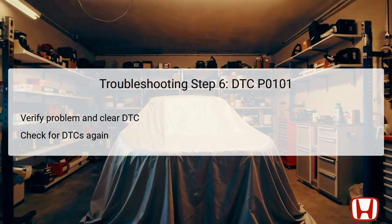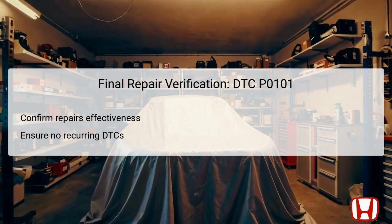If DTC P0101 appears again, this confirms that the issue persists, indicating a need for a MAF sensor or IAT sensor replacement. If no DTCs are present, this might suggest an intermittent issue or other external factors that could have caused it. In this case, ensuring proper connections at the MAF sensor, IAT sensor, and the powertrain control module, PCM, is essential. Final repair verification is crucial after addressing the DTC P0101 issue.